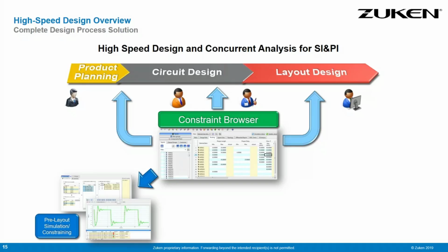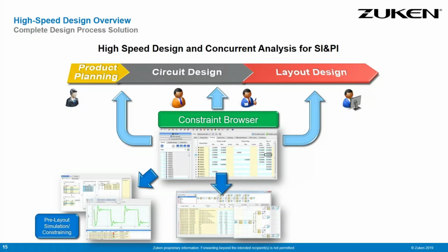You can run pre-layout signal integrity simulations to figure out what is the maximum amount of net length based on Manhattan distance, because it has to fit on a decent form factor. During the schematic design, you can create more complex rules. You can create the routing sequence by creating so-called topology templates.